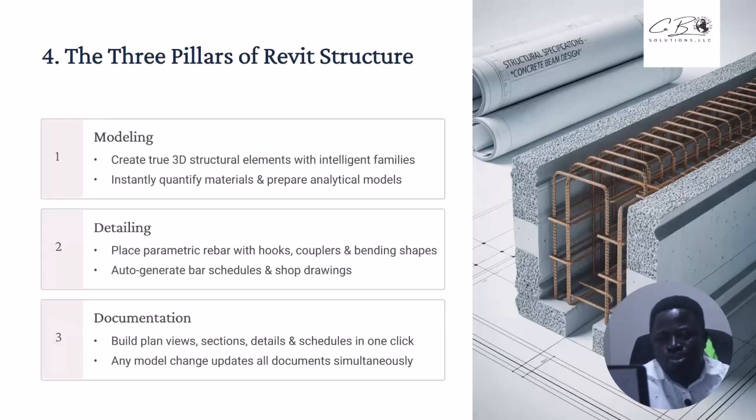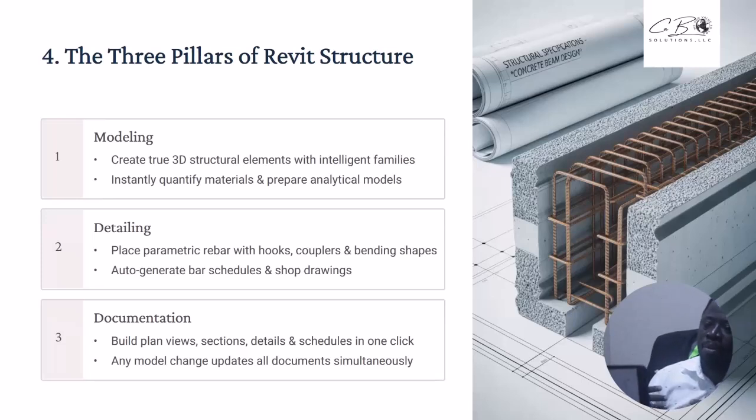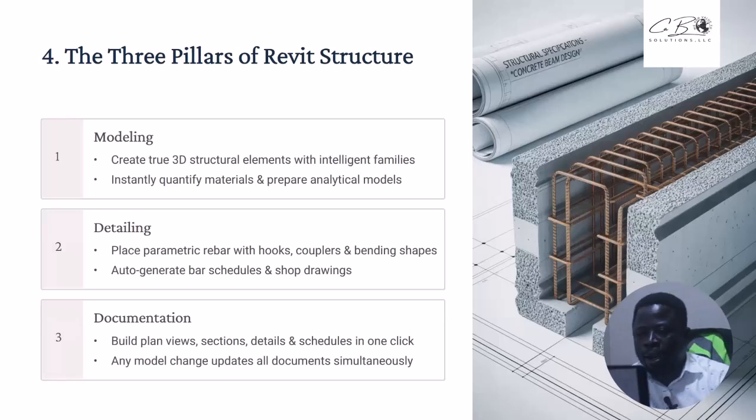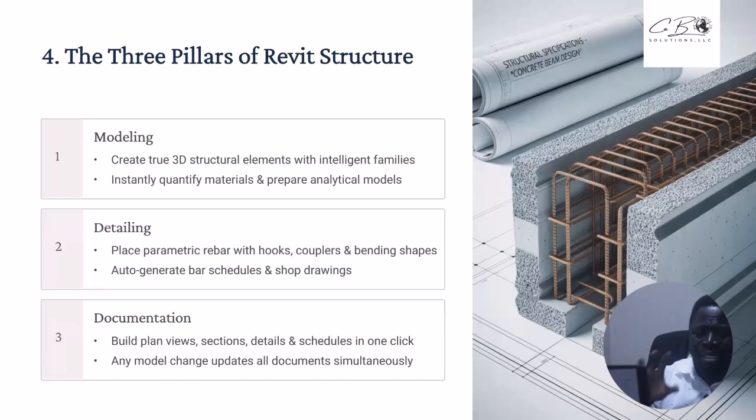The next pillar is detailing. Every element you can detail the bars, and in Revit you will see the 3D bars in the elements. When we get to the case study time, I'll open up a structural element and show you how it is, if time allows us. So detailing is done. You pick every element and then you detail it.